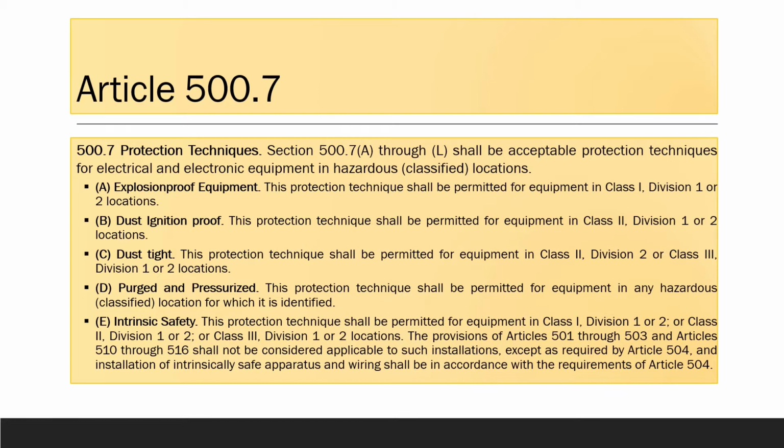This equipment is enclosed in a manner that excludes dust and does not permit arcs, sparks, or heat otherwise generated or liberated inside of the enclosure to cause ignition of exterior accumulation or atmospheric suspension of a specified dust on or in the vicinity of the enclosure.